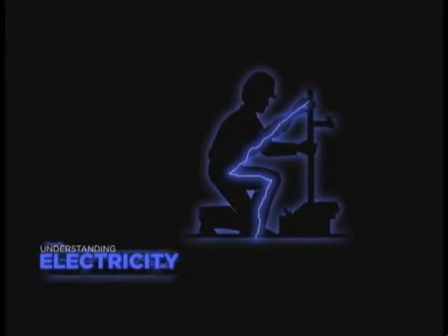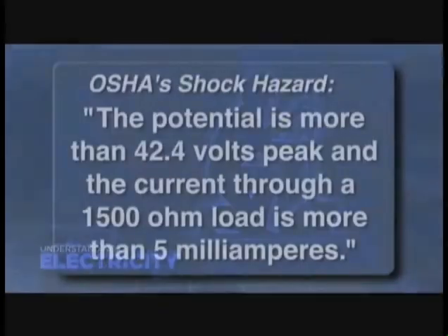Electricity passes very quickly through our bodies when we come in contact with it. The voltage and current of the circuit and internal body resistance will determine the severity of electrical contact. In some cases, electricity uses multiple paths to ground. The operator may get shocked when first touching a pipe or service meter. An operator may also get shocked when reinstalling a meter or service line because the operator completes the ground circuit.